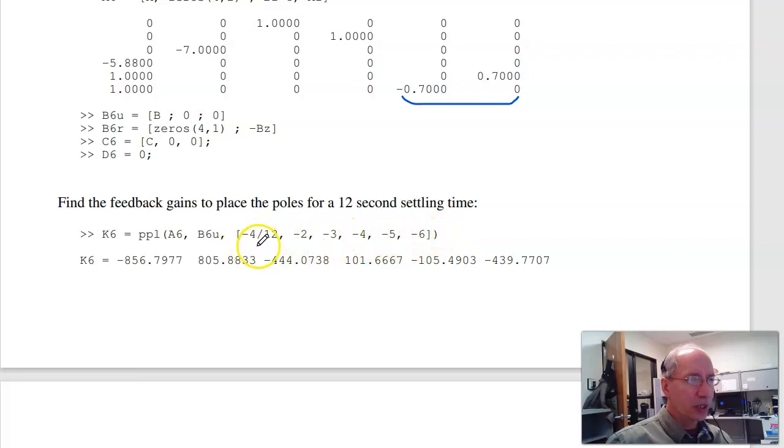If I change this to the B matrix with respect to U, this is what happens if I have a sinusoidal disturbance, meaning like the ball only weighs 2.5 kilograms. In that case, the disturbance goes to 0. It rejects the sinusoidal disturbance at 0.7 radians per second. So that seemed to work on paper. Let's try it in MATLAB.